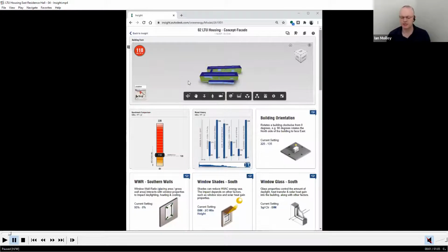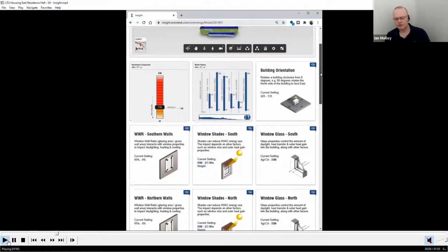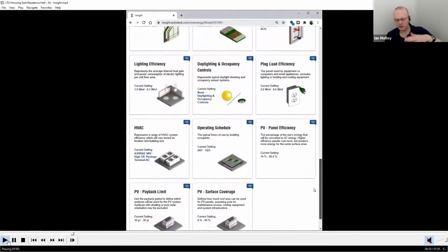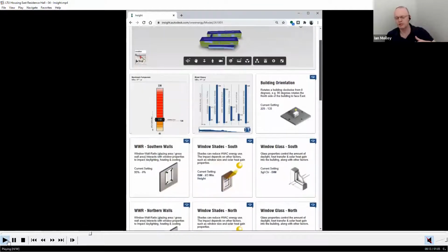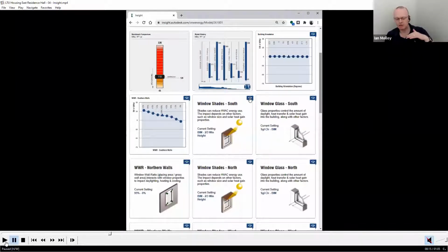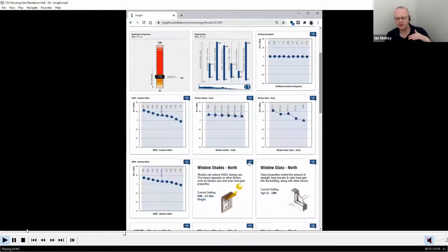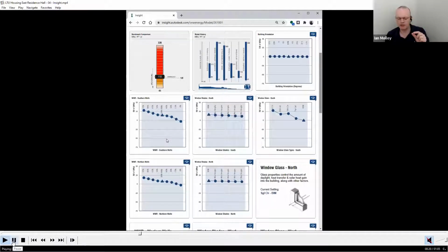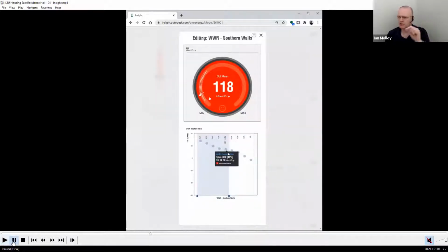So basically what you'll see here is the view of the analytical model. At the moment the metric it's showing is energy use intensity. You can flip that over just by clicking it to give you energy cost, and you'll see all of the factors change. If you look down through this list, there are about 24 key factors that influence building energy. These are essentially scales against which we have tested and weighed the model. If you look at that little triangle, that's whatever's in the Revit model, either from conceptual through the detailed geometry or any of those material settings.